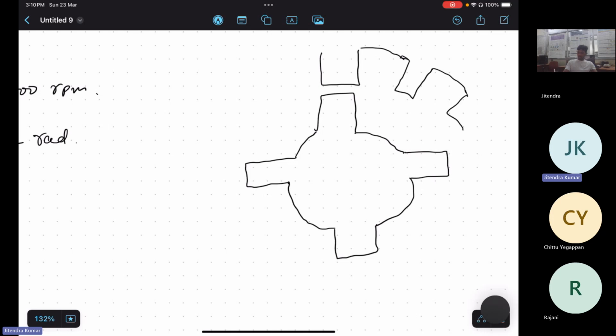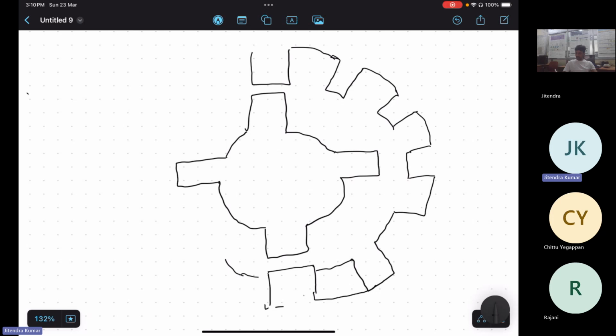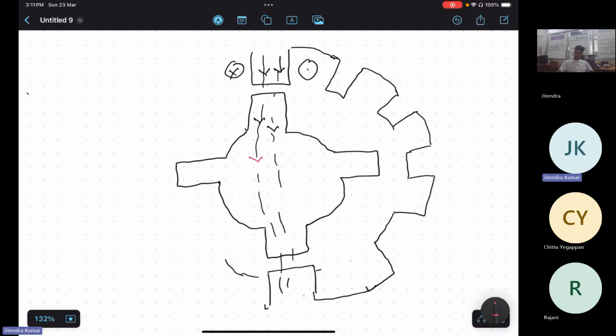Like that, a stator is placed. My drawing is not matching, but ideally it should be like that. Here also it should be a minimum reluctance path, so that maximum flux will link, and this is known as aligned position, right? And why is it happening? Here the windings are placed. So if you curl your finger from dot to cross, there will be a stator MMF, a stator flux direction from top to bottom, isn't it? Yes, sir. Like that.